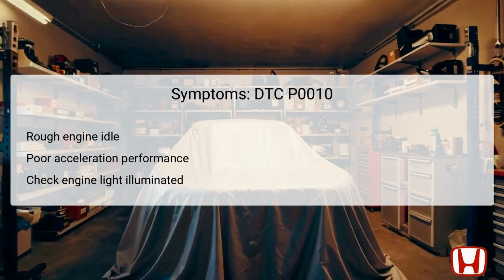The symptoms associated with DTC P0010 can manifest in several ways. One common symptom is a rough engine idle, which can indicate that the engine is not running smoothly due to improper valve timing. Drivers may also experience poor acceleration performance, making it difficult to gain speed efficiently.